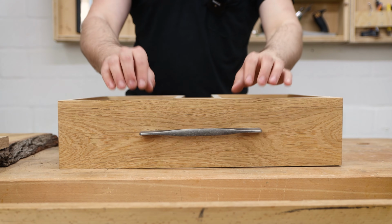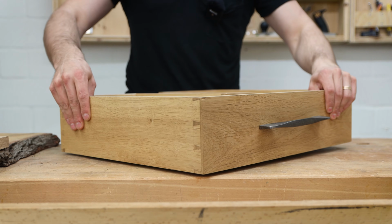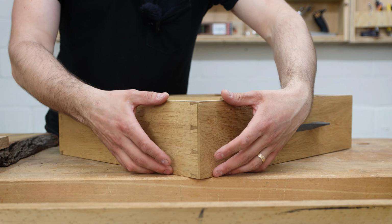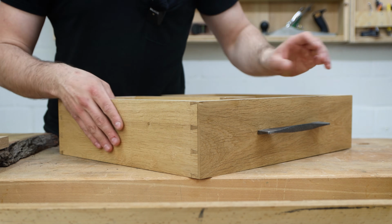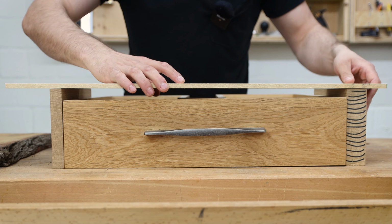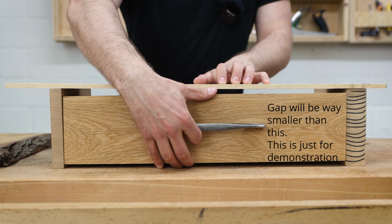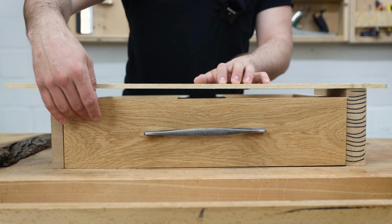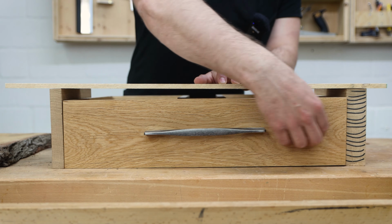Where wood movement also is a big factor is with solid wood drawers. So this drawer is all solid wood, as you can see. Here the grain is in the same direction, so it expands and contracts in the width of the board. And this means the height of the drawer is going to change here. So if this is our drawer front opening, something like this, we have to leave a small gap between the top and or between the bottom and the opening, because this width is going to change with the seasonal wood movement. We do not have to leave a significant gap here or here because along the grain it's not going to change its dimension.